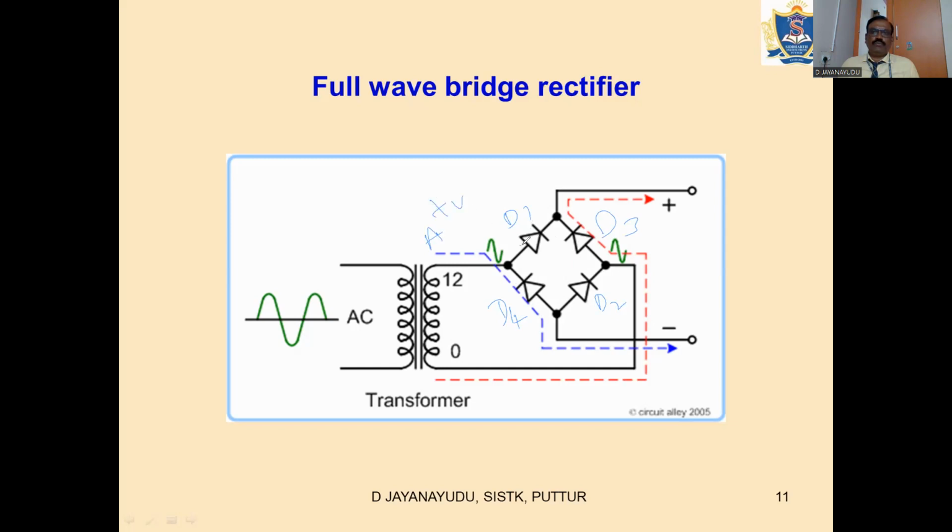B. So diode D1 conducts so that current flows from point A through D1. Okay. And then to the positive terminal. So this is my closed circuit through the load. Okay. D1, D2 conduct. D3, D4 won't conduct, open circuits. So D1, D2 will be closed circuit. So if you connect the load over here, now current flows in this direction. So that positive half will be transferred to the load.